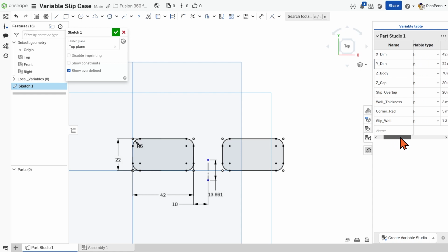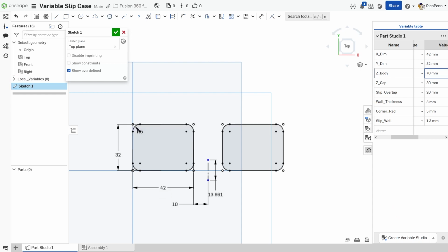And the great part of that is, being as how these have to be mating parts, they will always be the same size because they're mirrored in the definition of the parametric elements. So anytime I change half of the slip tube, the other half will always change with it. That's part of the wonderment of parametric modeling. So the reason we did these corner radius and this one is when we mirror it, they're already over here and I don't have to do them again.